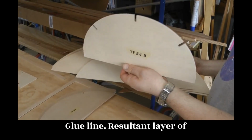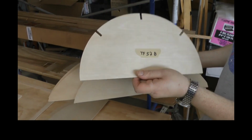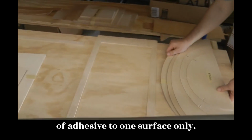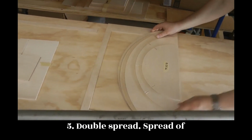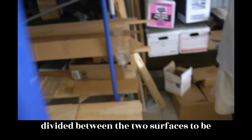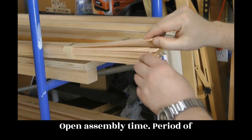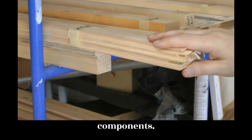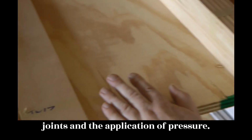3. Glue line. Resultant layer of adhesive joining any two adjacent wood layers in the assembly. 4. Single spread. Spread of adhesive to one surface only. 5. Double spread. Spread of adhesive to both surfaces and equally divided between the two surfaces to be joined. 6. Open assembly time. Period of time between the application of the adhesive and the assembly of the joint components. 7. Closed assembly time. Time elapsing between the assembly of the joints and the application of pressure.